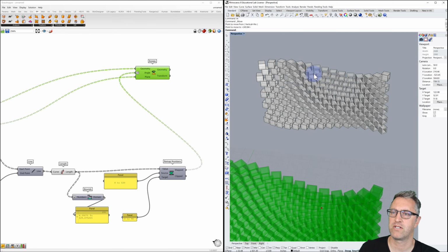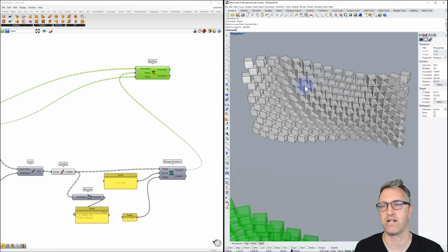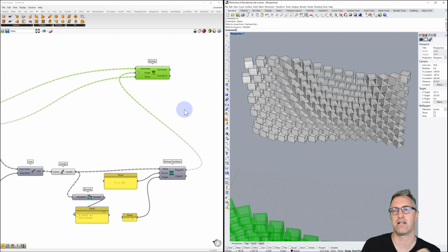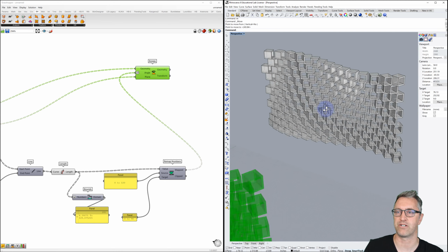So really simple, a relatively simple way. Hopefully this helps you understand. There's a lot in Grasshopper, there's a lot tied to the data structure, and in this instance starting to alternate the contour lines and also beginning to shift the points. It allows us to control that pattern at an early stage. Then it's easy enough to rotate all of the boxes around their own orientation.